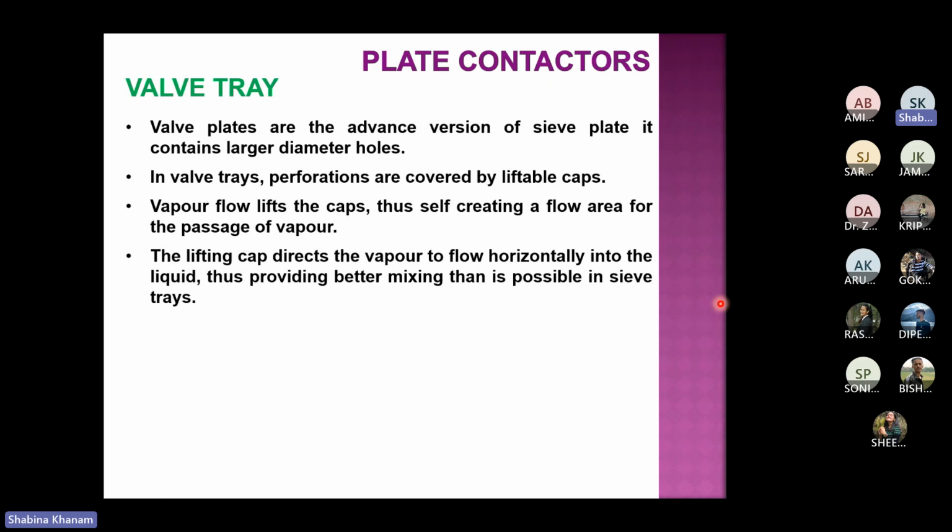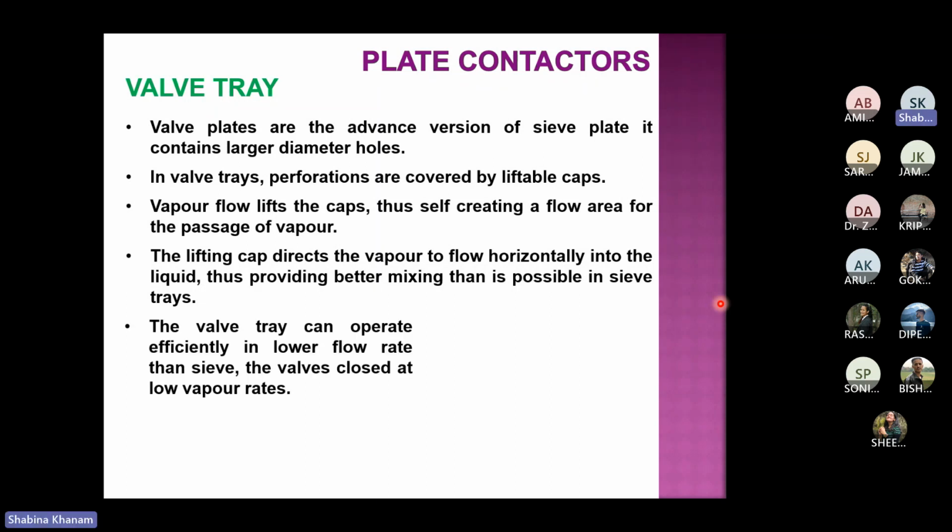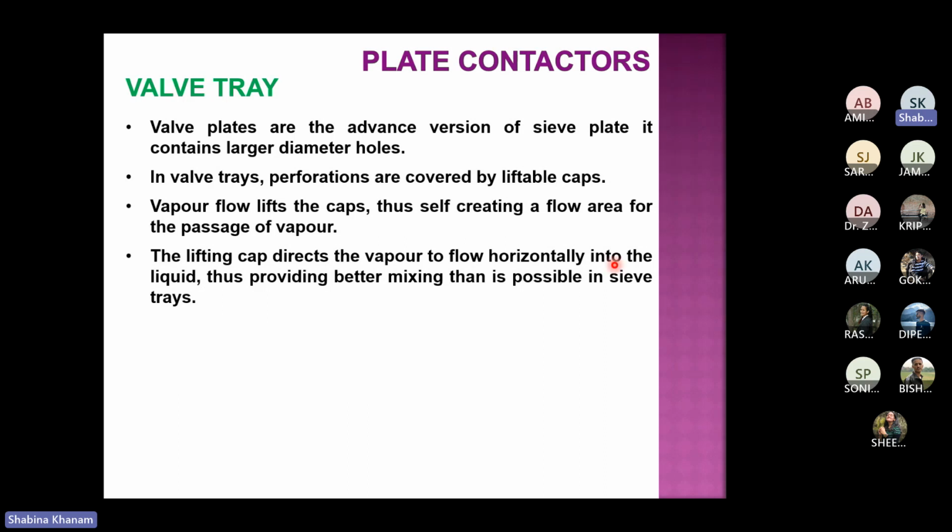But as it is the advanced version of sieve plate, it should also operate at low vapor flow. What is the point to consider? It should have a provision to address weeping, but it should not be of very high cost. Let's see how it will happen. So the valve tray perforations are covered by liftable caps.